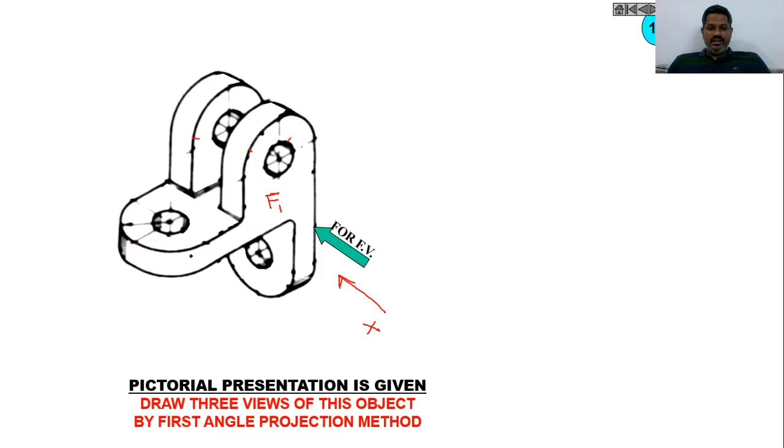So totally I'm assuming this as one surface, and finally we will get one dotted line here, two dotted lines to represent this hole, and similarly we will find one dotted line to represent this hole. So this hole we need to represent as a dotted line, and this hole also we need to represent as a dotted line here in two rectangular faces. And similarly we have to represent this circle as a thick line in front.